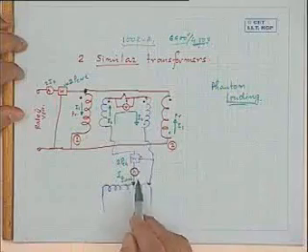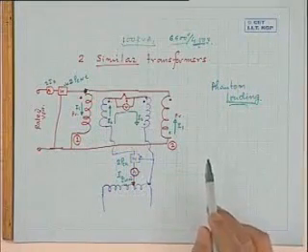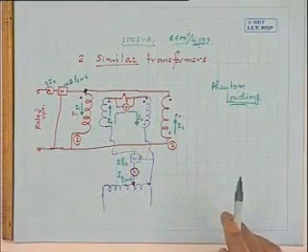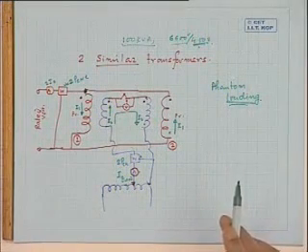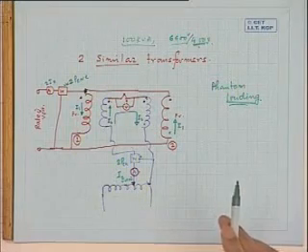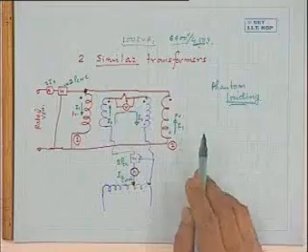So this way, if you test, you can come out with several things. Perhaps you can estimate the temperature rise by maintaining the rated current all the time by adjusting it. But you load it for significant time, say over a complete day, you keep it loaded. Then the resistance of the winding will change with the temperature rise in the transformers. From the readings of the wattmeters, you will be able to estimate the winding resistance, hence predict the temperature like that. Are you getting? So those things are possible.